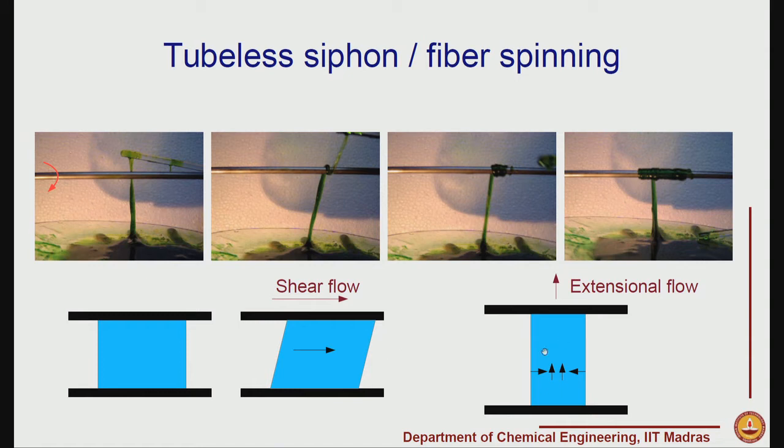In this case, fluid will come in radially, while in the axial direction it will move apart because the plates themselves are being stretched apart. So, when we have the filament, the diameter of the filament will become smaller and smaller, which means there is a radially inward flow, and the length of the filament will become more and more because there is stretching in that direction.